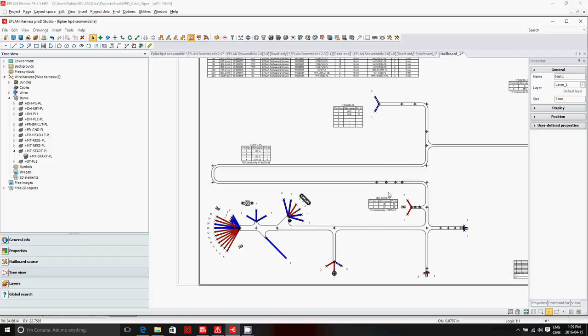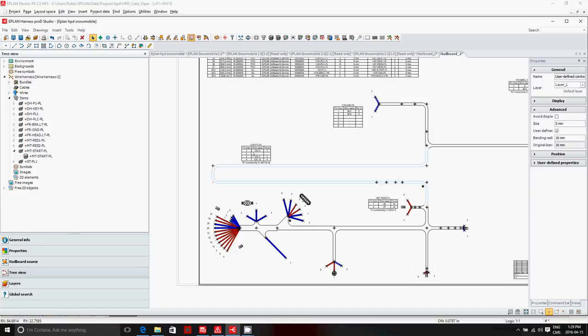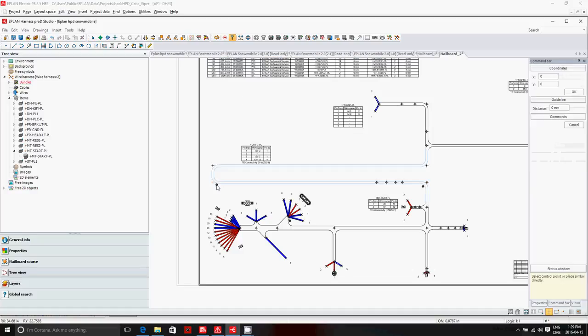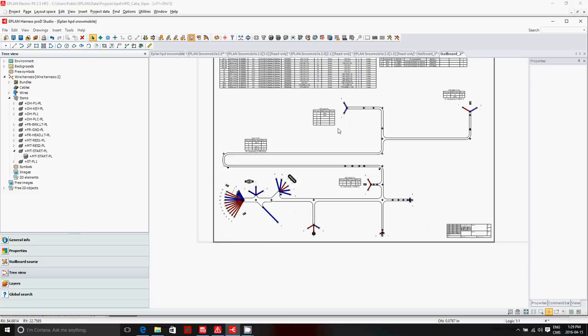So if you have a control point, let's say this is your control point, and you want to add a nail for this control point, the portion that is interesting is that, based on these control points, if they move in the 3D, the nail will move with it. So that's the nice portion of it. You can of course leave it up there, and the guys will put their nails by themselves. These are just tricks and tips that you want on top of it.